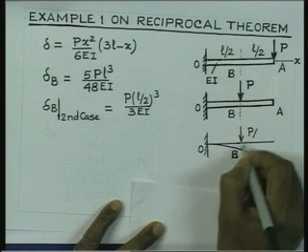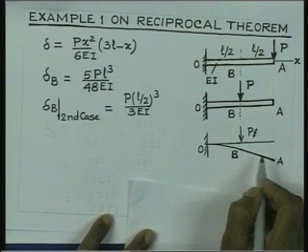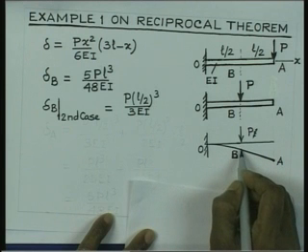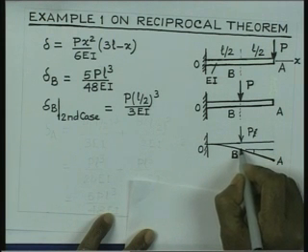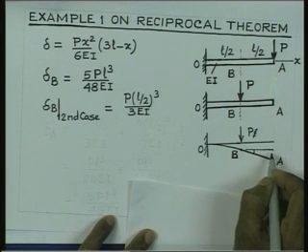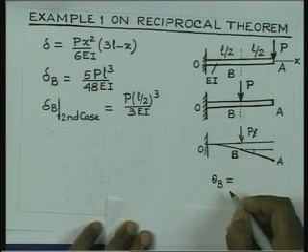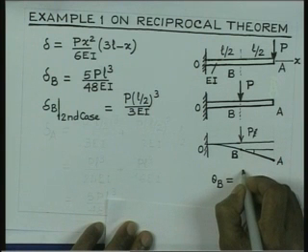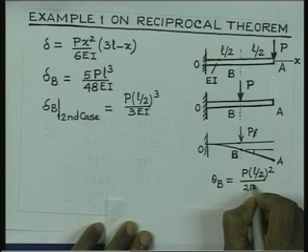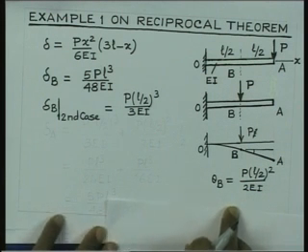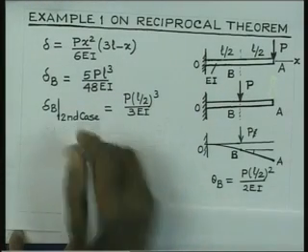I am sorry, under the action of the force P acting at this point. Now, if I have to calculate the deflection at this point, we can consider deflection at A is nothing but deflection at B plus the rotation here at point B multiplied by this distance L by 2, and this rotation at the point B in this case is given by the formula P L square by 2 E I, and therefore, it is P (L by 2) square by 2 E I. So, that is the rotation, and therefore, we can now calculate the deflection at the point by adding up